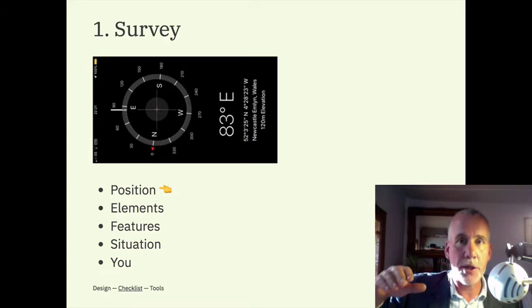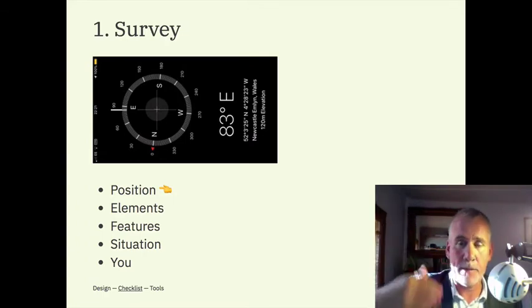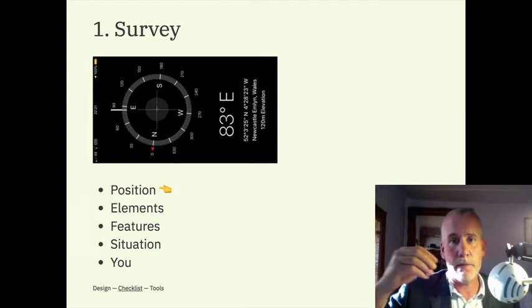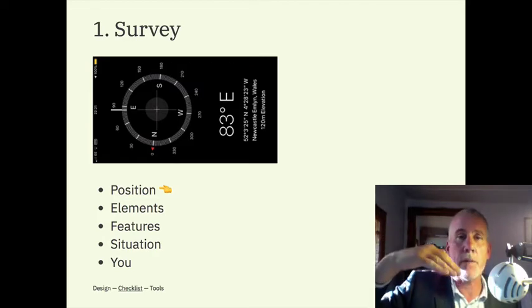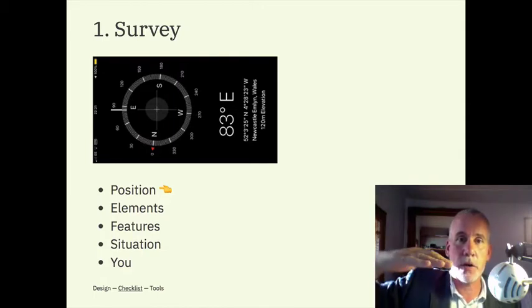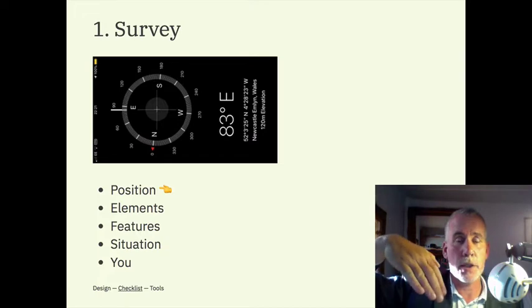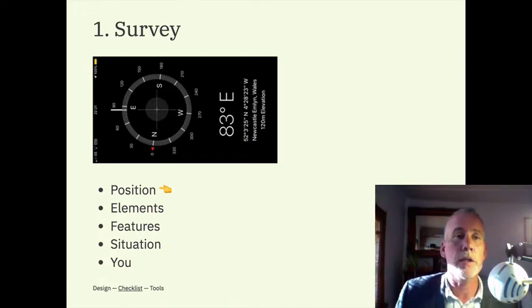The other thing to look at is the elevation, how high up you are, which will determine the weather and the climate. And finally, the slope. If there's a slope on the land, that has a big bearing as well. If you're north facing and on a slope, you're going to get significantly less sunshine, whereas if you're south facing, you get more sunshine. If you're south facing on a slope, you're going to get even more sunshine, to put it crudely. So you need to work out your orientation, your elevation, and the slope.